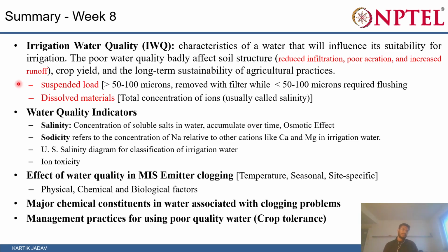For suspended load, we have two conditions: either the suspended load has a size greater than 50 to 100 microns, in which case we require filter-type material to remove it, while if it is less than 50 to 100 microns, we require a flushing technique. While for dissolved materials, it is the total concentration of ions, usually called salinity.